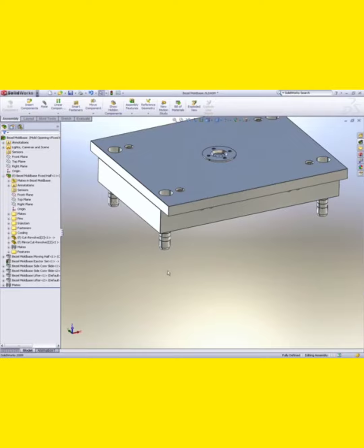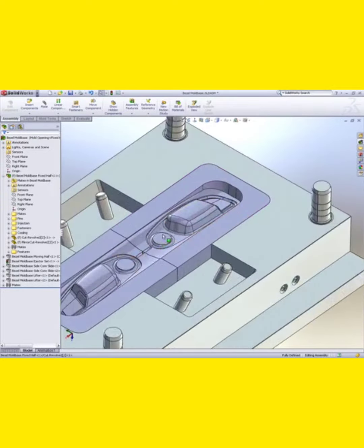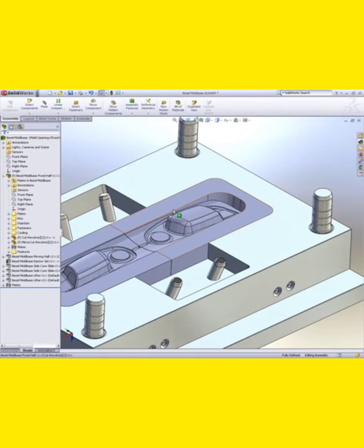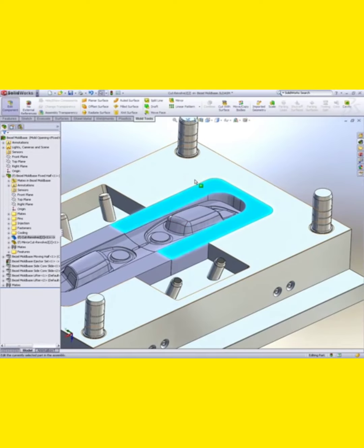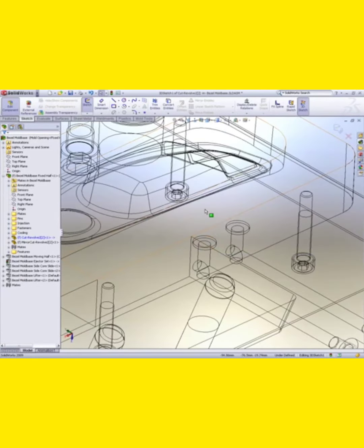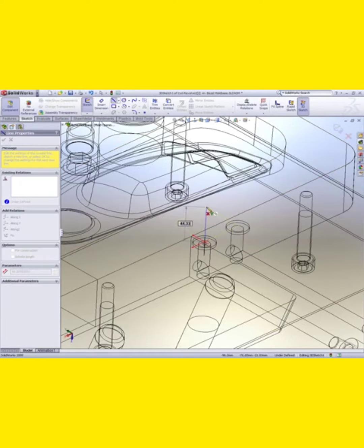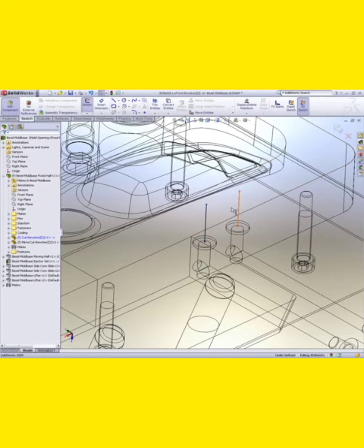Finally, we need to consider how this mould will be cooled. On the fixed half, we see that we already have some waterlines created in the bolster plate. These can then be continued into the insert, referencing the location of the O-ring recesses using a 3D sketch. A 3D sketch is a convenient way to draw the path of the waterline in all 3 dimensions at the same time. Here we are drawing vertically in the Z-axis and ensuring that both lines remain the same length.